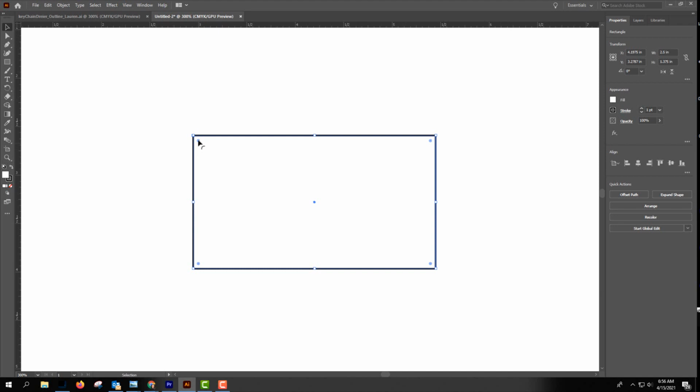The example that I'm going to have in class has a 1/4 inch fillet, so I can grab this, left click and drag, and watch the indicator on my screen as I go closer to 0.25, which is 1/4 inch. I can keep dragging to the center, and that allowed me to fillet all 3 sides.